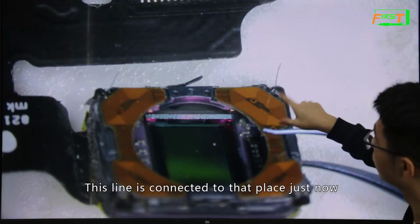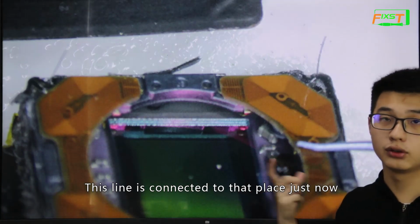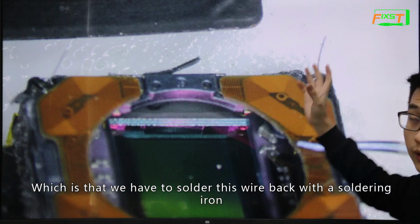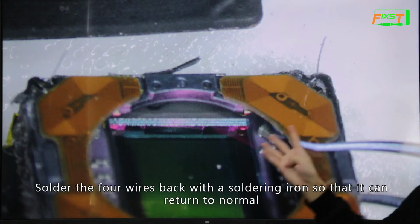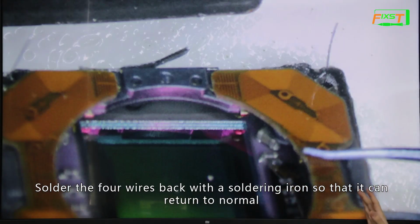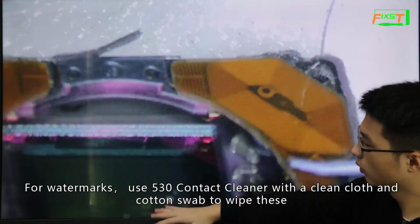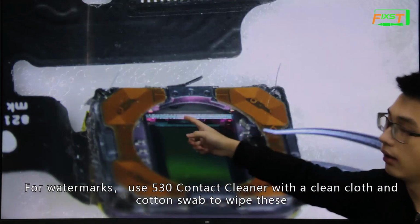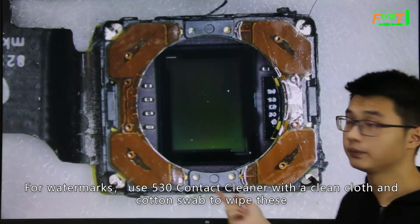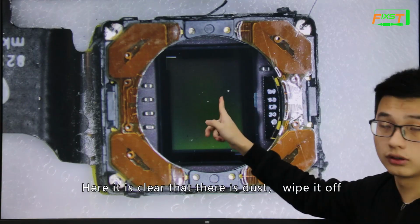The line is connected to that place just now, which means we have to solder this wire back with a soldering iron. Solder the 4 wires back with a soldering iron so that it can return to normal. For watermarks, use 530 contact cleaner with a clean cloth and cotton swab to wipe this. Here it is clear that there is dust. Wipe it off.